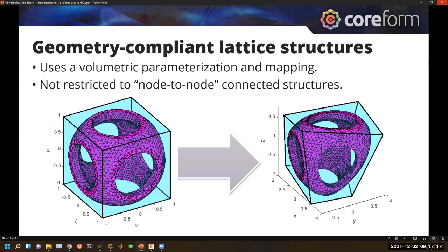And as a keynote, again, what's happening under the hood is we're just borrowing a lot of concepts from finite elements. So we take the geometric mapping of a finite element, and I've shown here the unit cell as a tessellation of triangles. So each point in this tessellation has a mapping to the element in its deformed configuration when you've meshed the part.